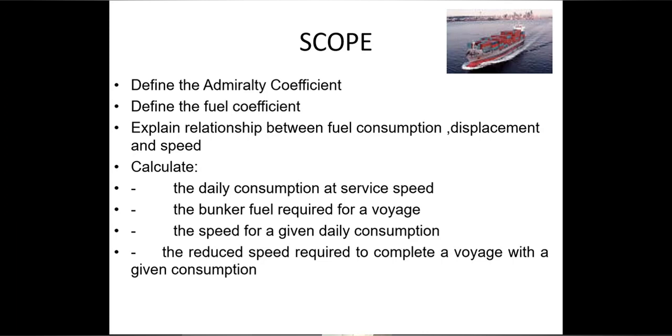Many times we know that we have a certain amount of bunkers, let us say 2,500 tons on board, and we know the voyage distance remaining. For example, even out at sea, suppose we know that so much is the distance to go. At what speed should I proceed so that I arrive at port with sufficient bunker? Sufficient means that the bunker on board at that time should be sufficient for the vessel to reach port. And what will be the ROB? We consider that this is unpumpable.